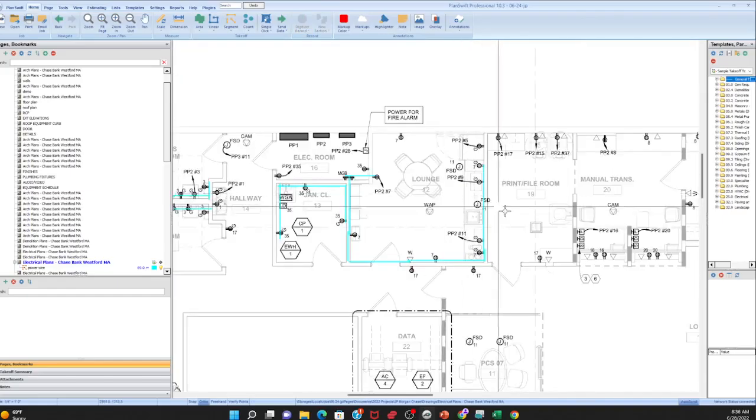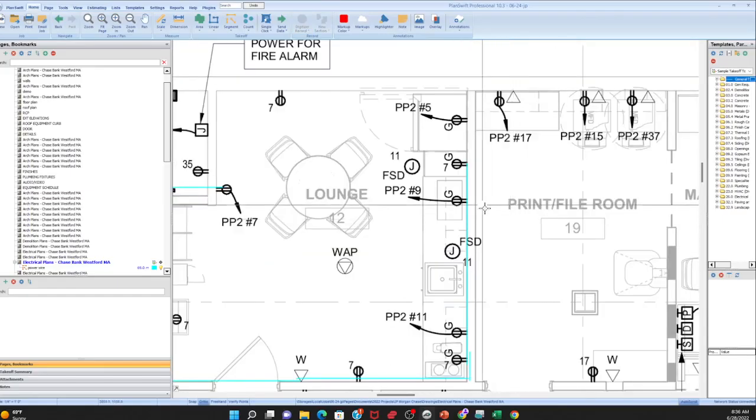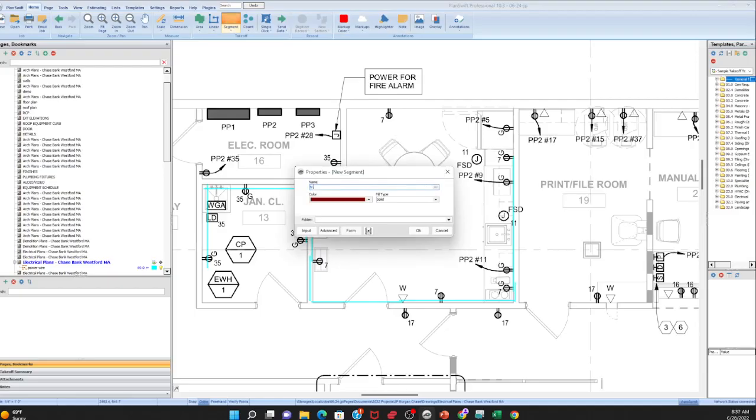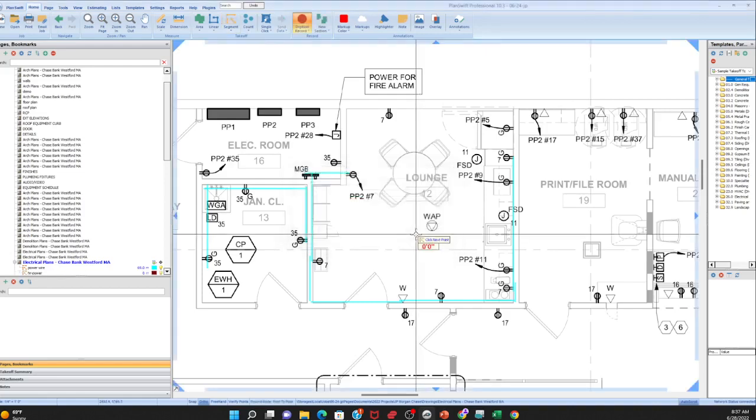Okay, so once I do all of these that I know are daisy chained together, I'm not finished. But assuming we're finished, this number 7 needs to come down too. Just keep that in mind. So assuming that I'm finished, now I'm naming something home runs, and then I'll name them power home runs because I separated out the lighting home runs too when I do the lighting plan.